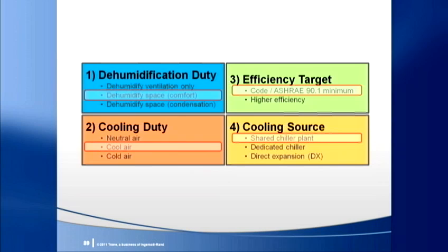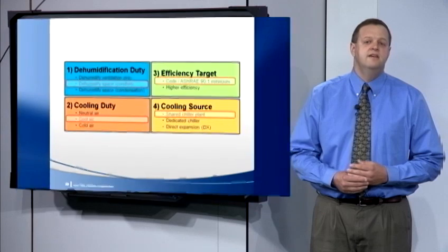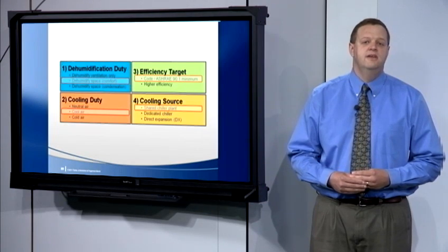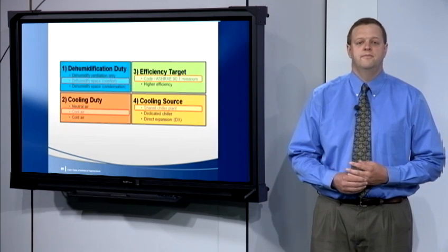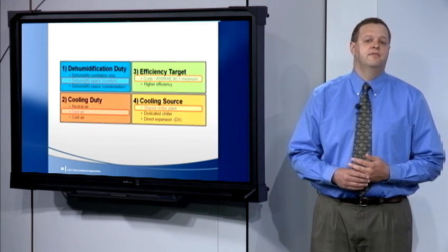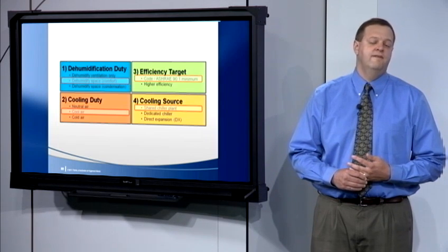As an example, if the system requires 46-degree dew point air from the dedicated outdoor air unit, what can we do if the only source of cooling on the project is a central chiller plant that makes 45-degree water? A cooling coil can't make 46-degree air if it only gets 45-degree water. An alternative is to use a Type 3 desiccant wheel in series with the cooling coil. This can also meet the prescriptive energy recovery requirement of ASHRAE 90.1.